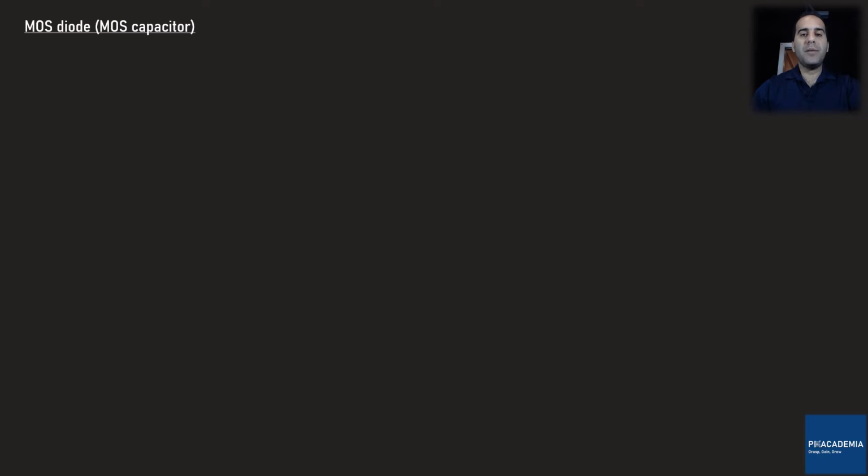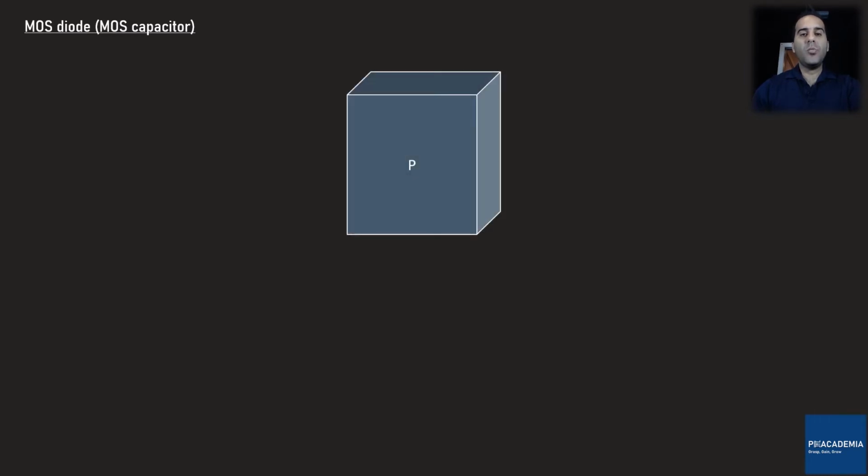A MOS diode or capacitor is made of a single P or N-type semiconductor. Let's consider a PMOS capacitor. Note that when I'm talking about the MOS diode, I do not mean it rectifies current. Diode simply means a two-terminal device.